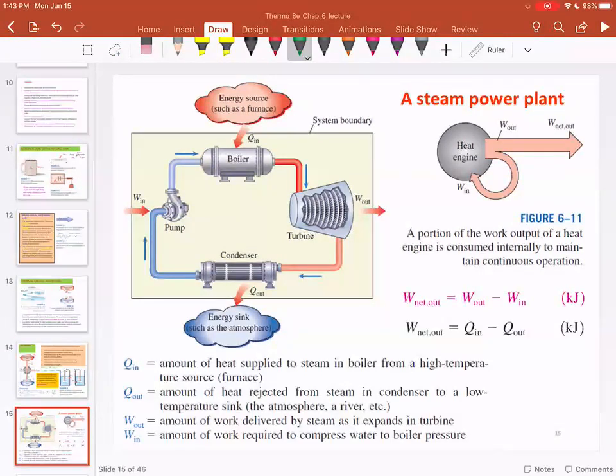It's a steam power plant, but they use natural gas as a fuel to do the external combustion. So again, the principle is simple. You have water that is pumped to the boiler, and using natural gas or any other means like coal or some nuclear reactor, the heat is generated. That heat heats the water, the water gets converted to steam.